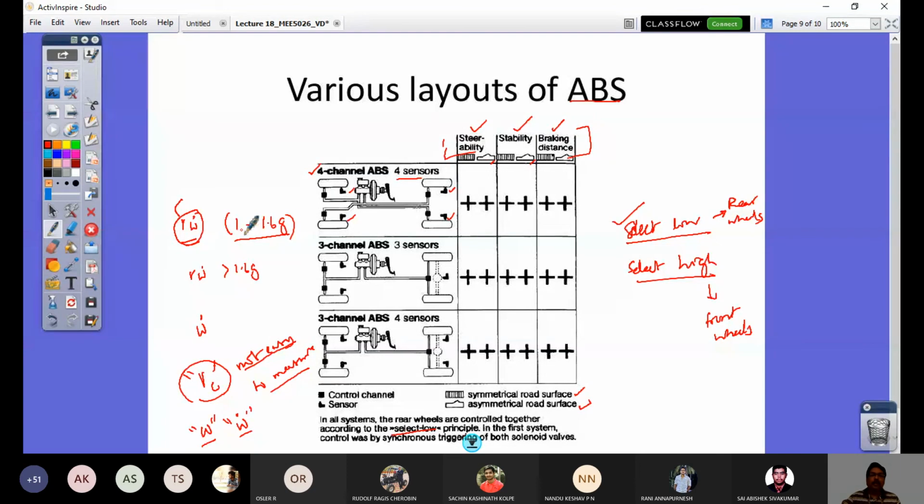So the modulation has to again act to increase the pressure. It would wait for 5% of the speed reduction. Whatever the angular speed omega was, if it is reduced 5% from the previous value, then again it will compare with the linear acceleration r omega dot and the vehicle measured acceleration, which is equal to Fb by Wg.